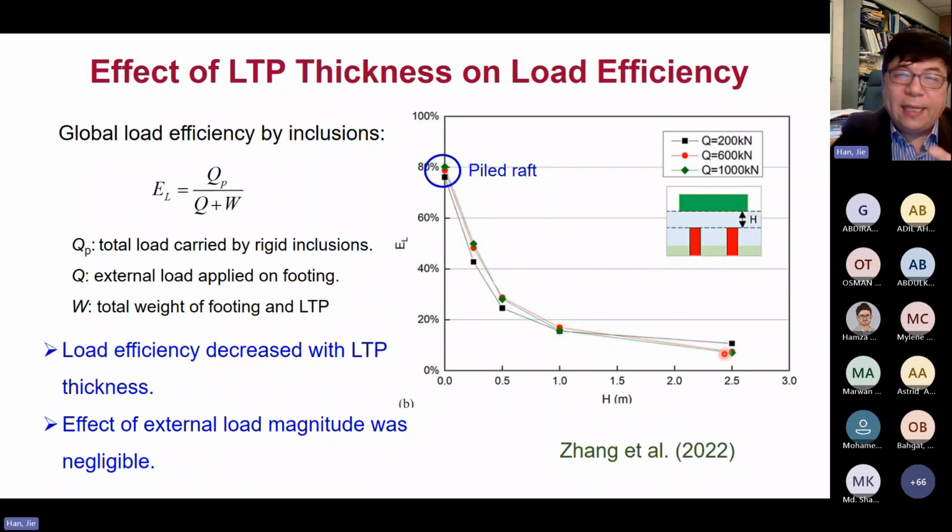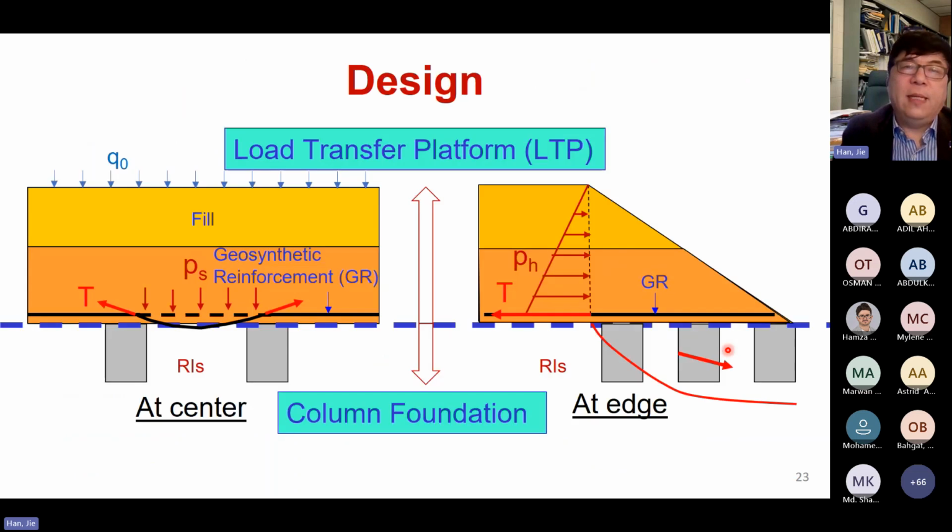Okay, so basically by placing the cushion and transferring more load to the soil, we ask for less support from the rigid cushion. This is also the reason why you can space the rigid cushions at the largest spacing that we talked about before, 2% to 10%, that is the percentage of rigid cushion, because that way you can utilize the rigid cushion more.